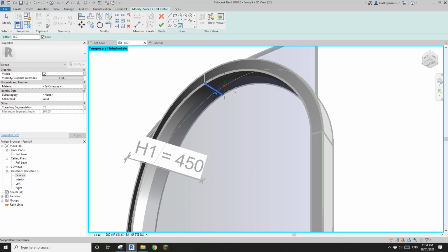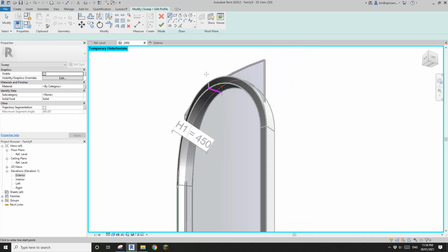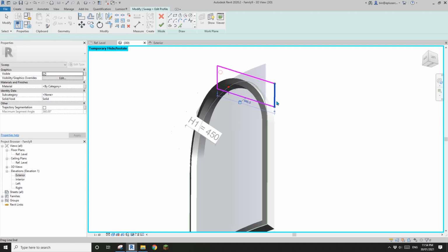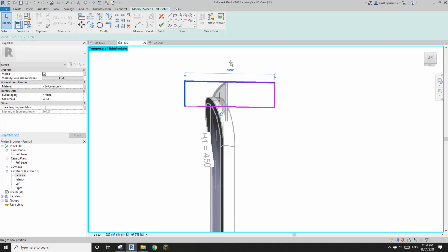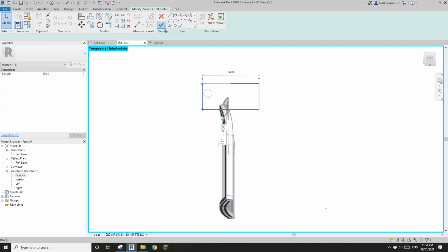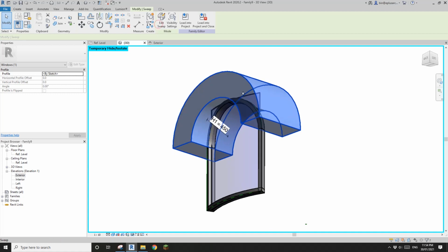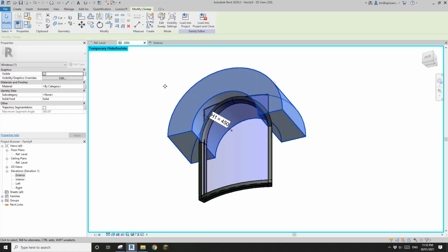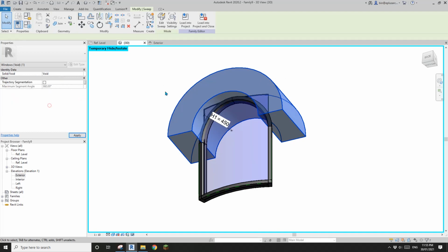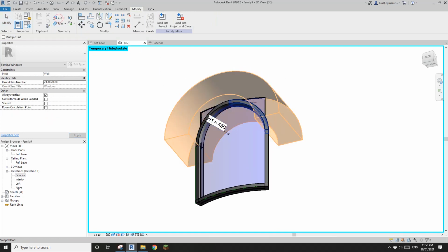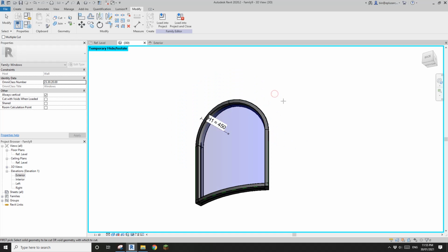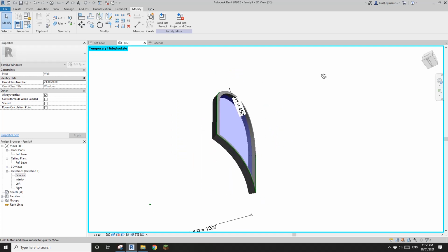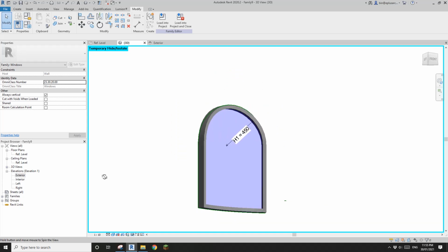And we're going to pick this edge to create a profile that covers the glass panel. Okay, so roughly something like this, and finish. So now this time let's do it again. Select this solid, create a void, and use cut, this glass, cut this. Yes, it works. Okay, so yeah, that's it.